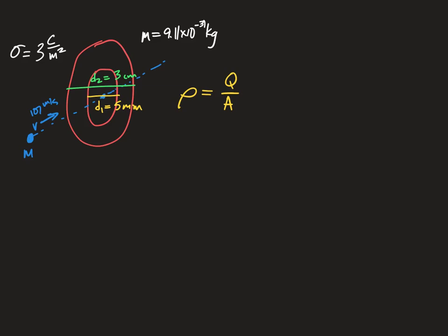So we have a way to do that. The total area of this particular thing would be basically area 2 minus area 1. Which is going to be pi r squared, that's our favorite go-to for a circle, but I was given diameter dimensions, so r is d over 2, so r squared is d squared over 4.